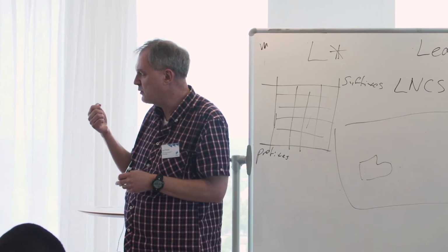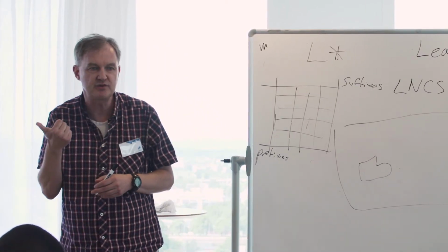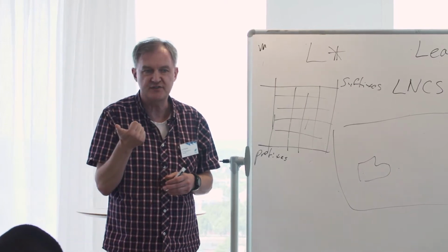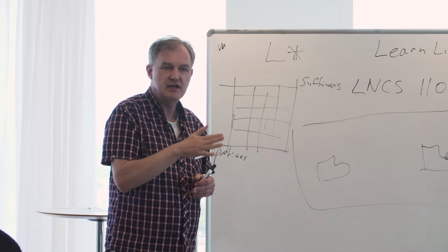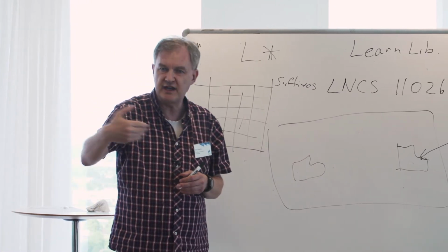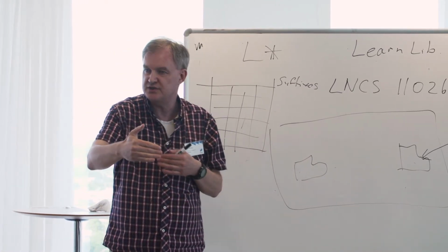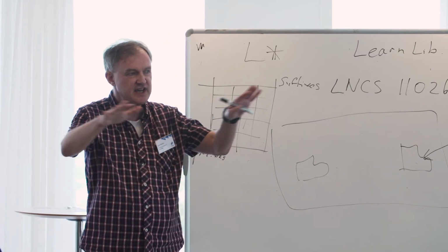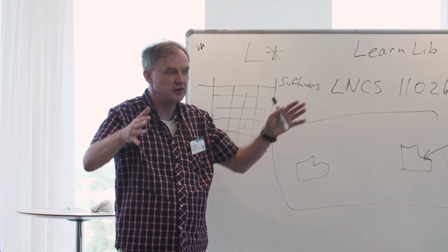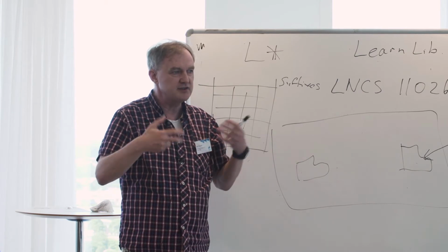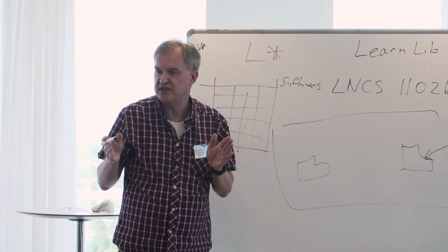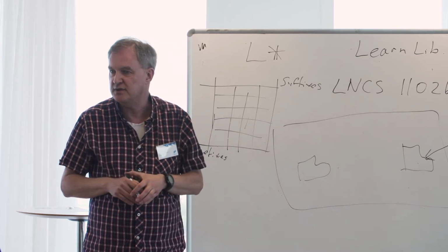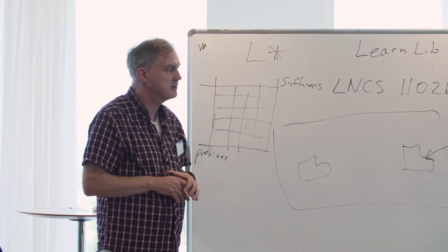So for a platoon, there would be use cases like high-speed cruising on a straight piece of motorway. There would be joining the platoon, leaving the platoon, changing lanes, a vehicle entering in between two platoon vehicles and so on. So you have to take the continuous world and pull out stereotypical situations of reasonably short time length and analyze those, okay? So this is the kind of work that we do.